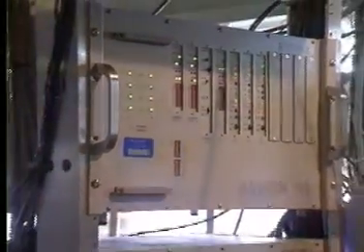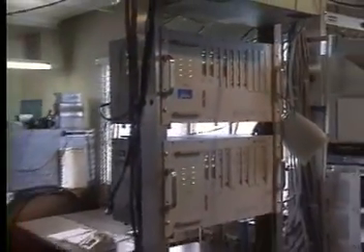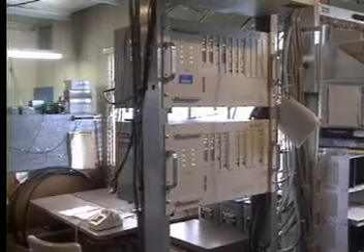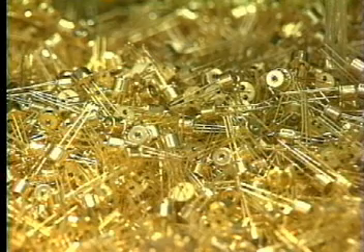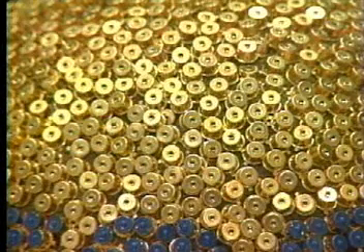At the opposite end of the fiber system is the receiving equipment, the heart of which is the optical detector. Detectors perform the opposite function of optical sources. They convert a flow of photons to a flow of electrical current. The simplest form of photodetector is the PN photodiode.